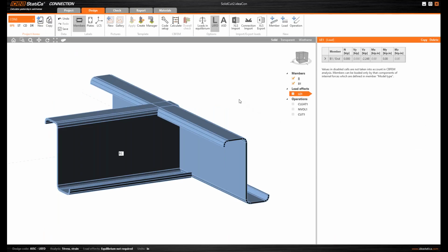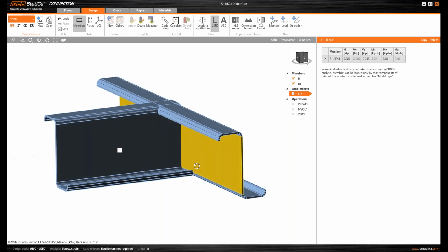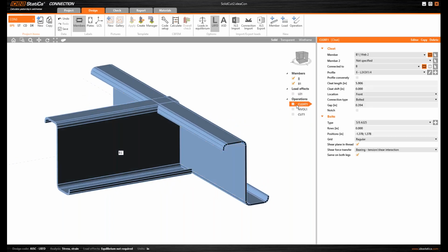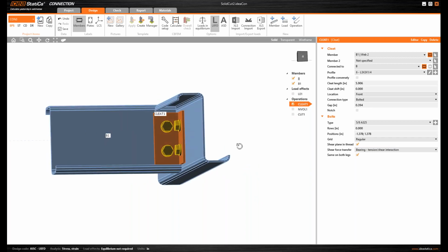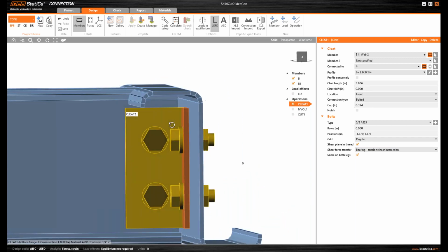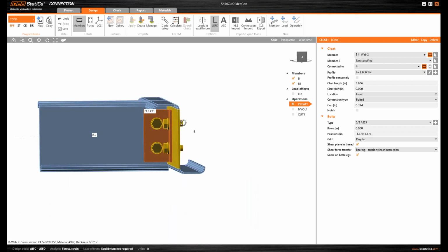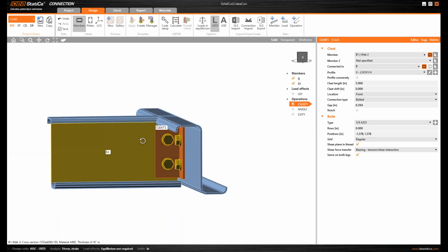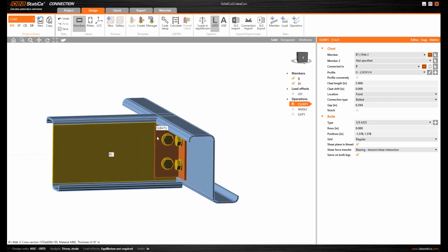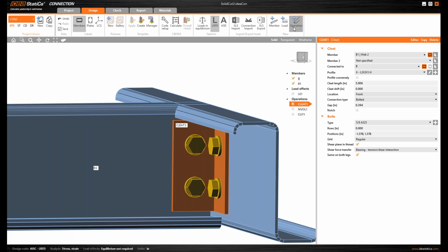And the new manufacturing operation, let's say I have this kind of topology, and I want to connect these beams together by cleat operation. And that's a typical one. But as you can see, there is a clash of the members at this top part. Yes, I can use a notch, but it's not so nice. It will create a not so nice cut. So I will use a new manufacturing operation.